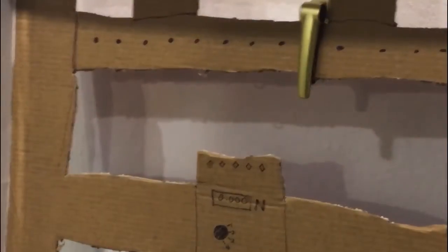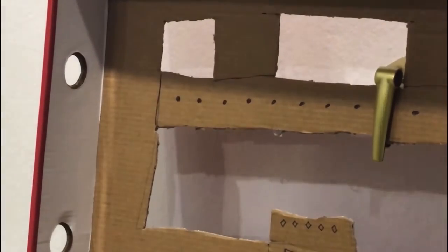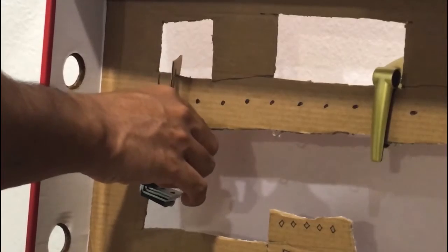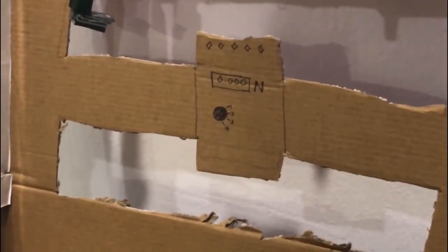Once again, check the digital force display meter reads 0 with no load, and then carefully apply load on the beam with the hangers in the position shown in figure 2S13 using the loads listed in table 2S13.